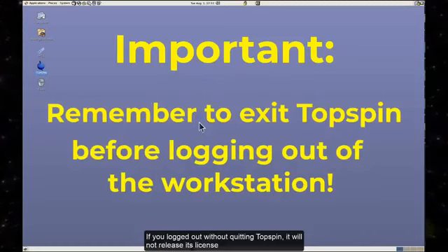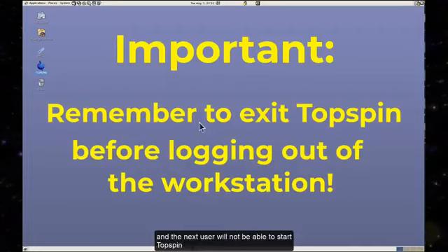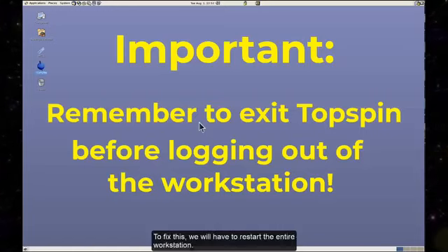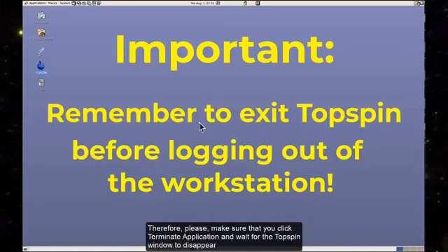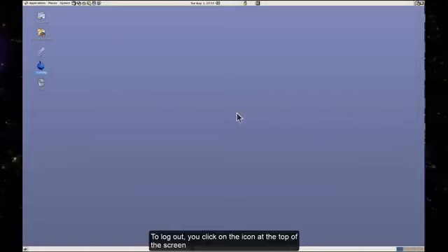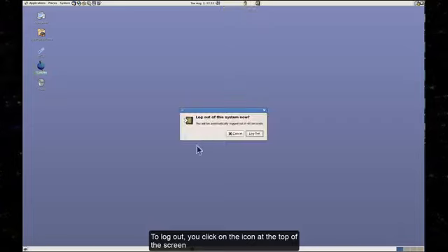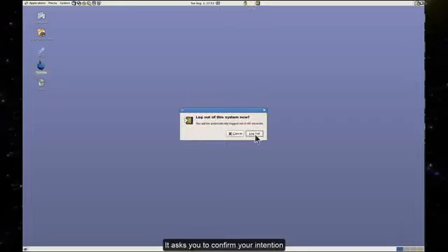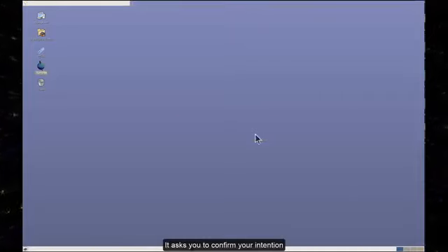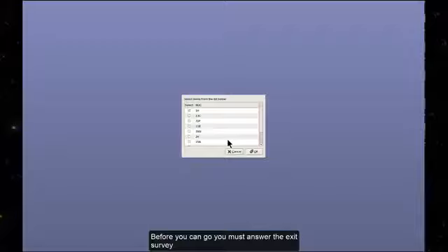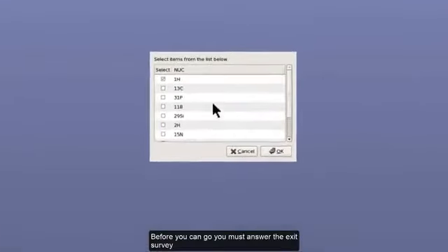2. Synthesizer, SY, and frequency generator, FG. These modules generate a stable, highly precise RF carrier wave at the exact Larmor frequency required for the nucleus, e.g., 60.013 MHz for ¹H. 3. Pulse shape generator, PSG. This module takes the digital instructions from the computer and the carrier wave from the FG. It digitally creates the specific shape, duration, and phase of the RF pulse, e.g., a square 90 degree pulse,